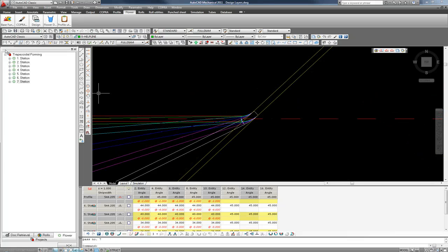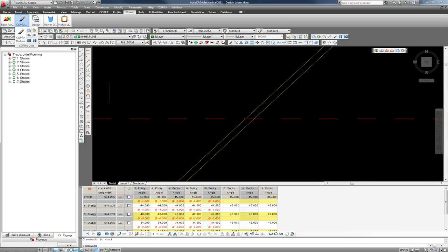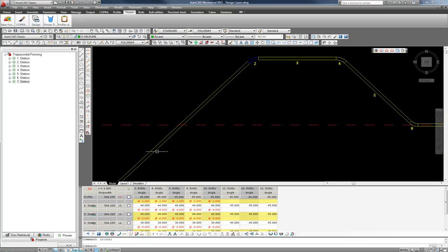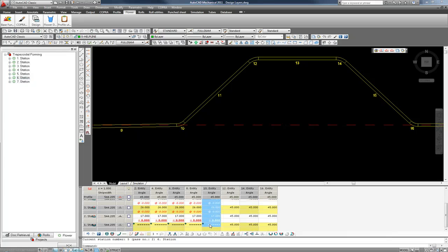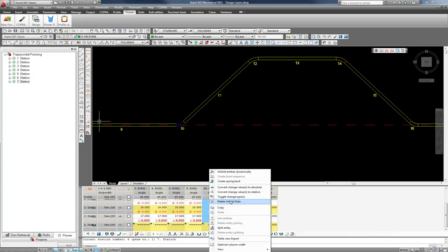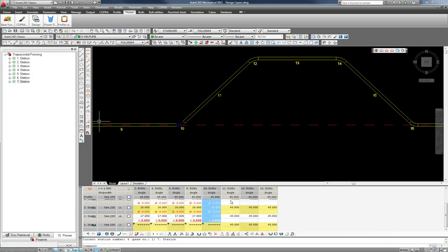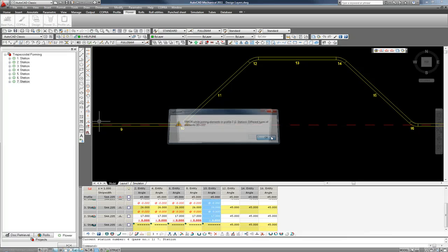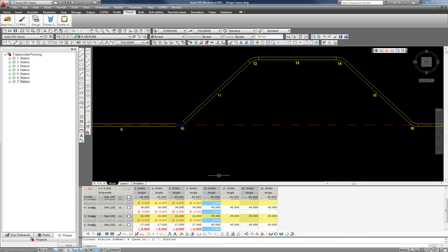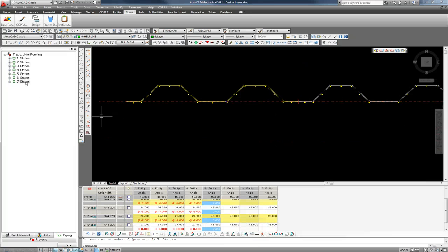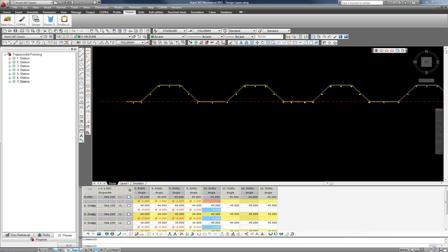So I actually began, if we review this here, to unfold station 6 entity 10 by mistake. I can now go here and right click and delete the unfold data. And now you can see, if I save this, our CSP file has been corrected.